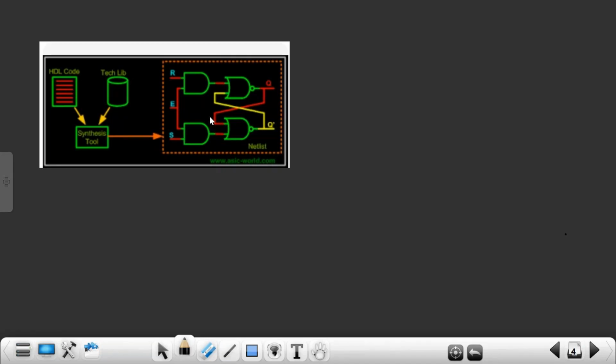So we will get a library file called a .lib file from a library characterization team. That information we will give to the tool. In this .lib file, we have all the standard cells available for conversion. Ultimately, my design will convert into those cells only.